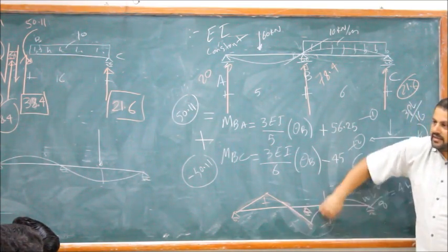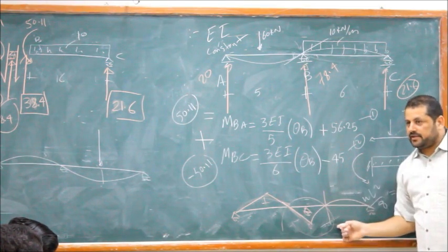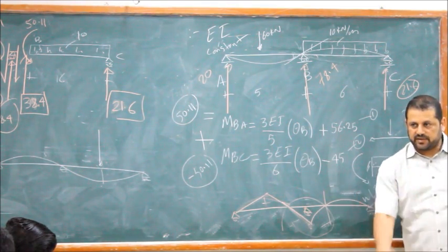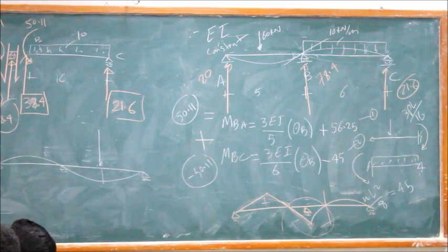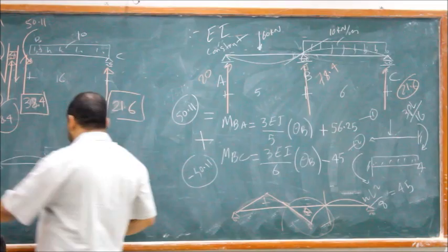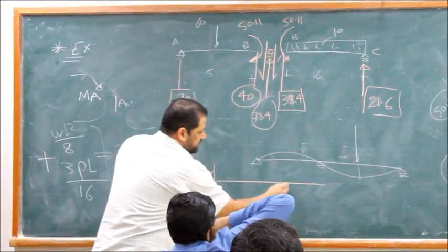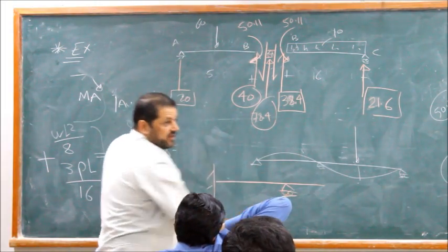So this area has negative moment. The reinforcement at the top. Here and here, positive moment. Reinforcement at the bottom. Next lecture, I'll show you how we take care of this. Next lecture, I'll show you this. You have an overhang.